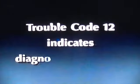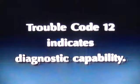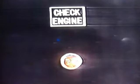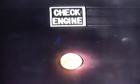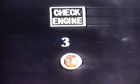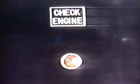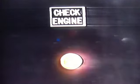Just as the 1-2 flash of code 12 indicates diagnostic capability, other flash sequences indicate other trouble codes. For example, 2, then 3 flashes is a code 23, while 3, then 2 flashes is a 32 code. As you can see, the first flash is the first number of the code, and the second flash is the second number of the code. As you watch the check engine light flash code numbers, you'll want to write each of them down. And no matter how few or how many codes have been stored in the computer, the sequence will always begin and end with the 12 code repeated 3 times. This is to let you know that you've seen all that is stored in the memory.